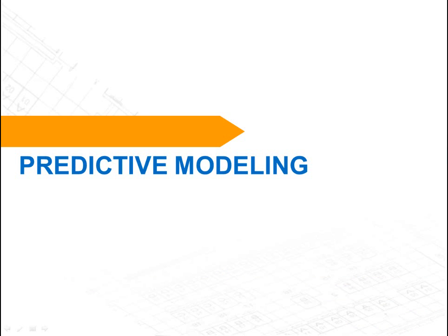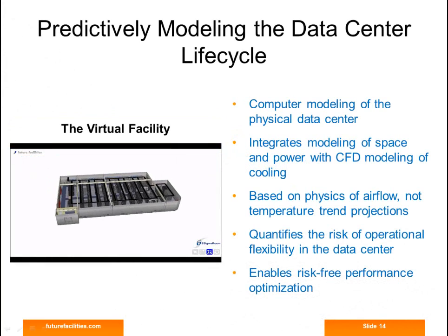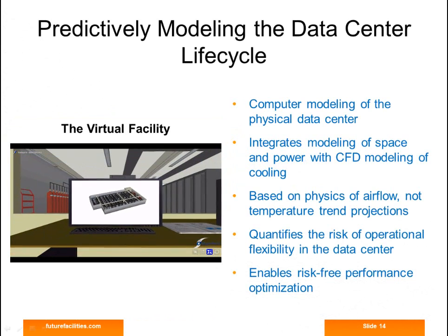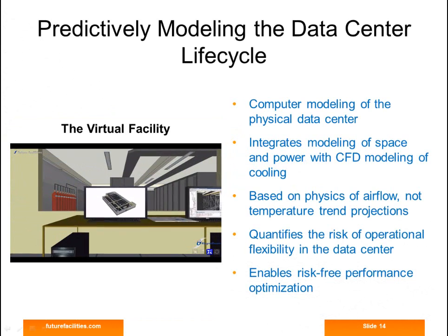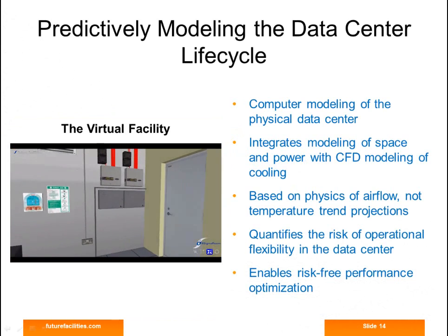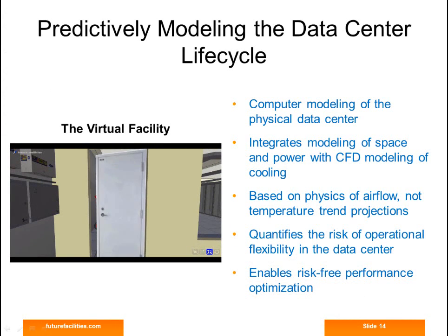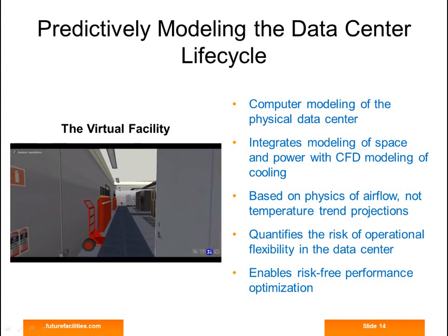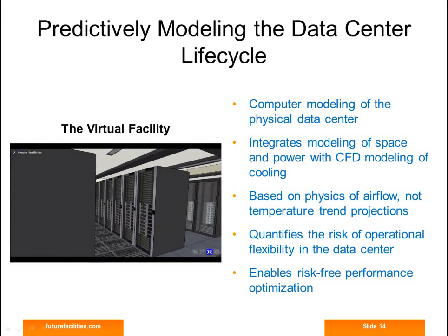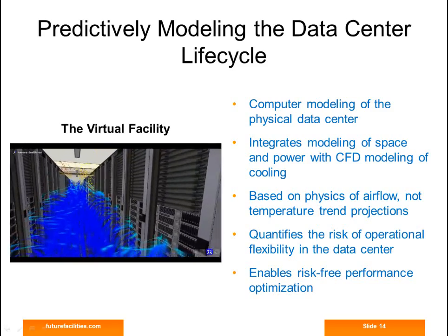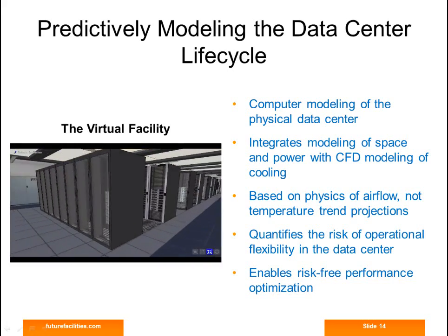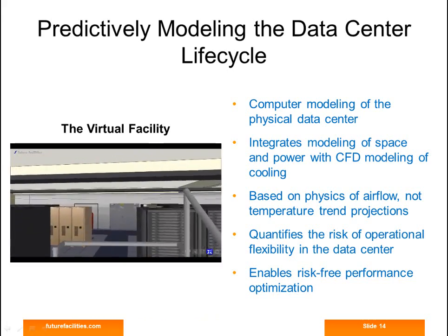So this brings us to predictive modeling. At Future Facilities, we call this form of predictive modeling the virtual facility. The virtual facility is a three-dimensional computer model of the physical data center at any point in time: past, present, and most importantly, the future. The modeling techniques combine modeling capabilities for space, power, and granular CFD modeling of airflow to predict the impact of changes to the data center health, the capacity of the data center, the availability of the IT equipment, and the performance of the data center itself.